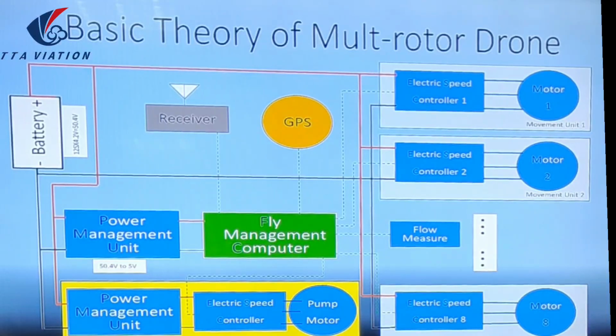So actually, the CAN hub has a part of PMU's function, because even though the CAN hub can directly link to the battery and output a 12-volt voltage, the power of the output port is not very strong. It can only support some low power use devices.